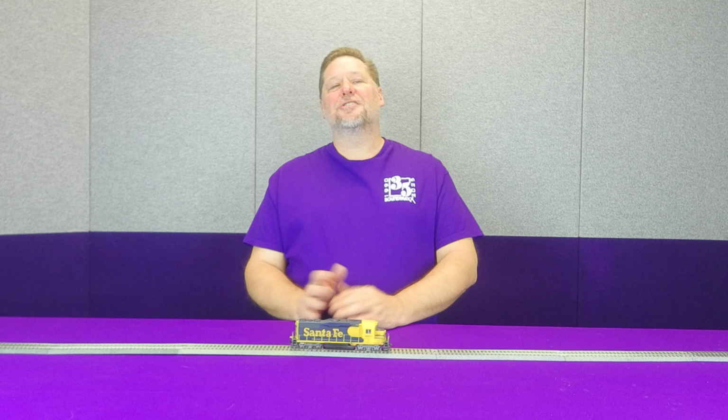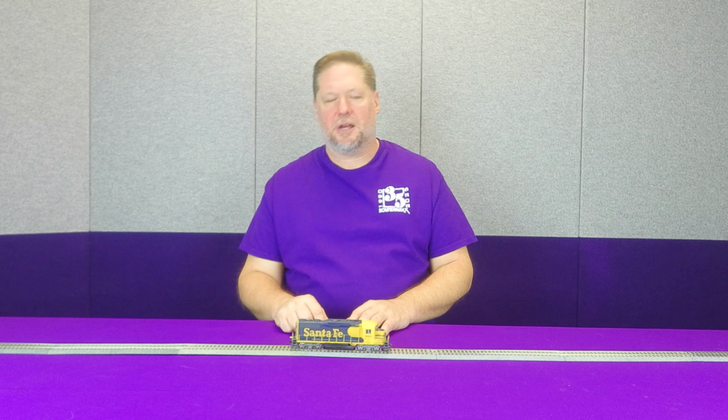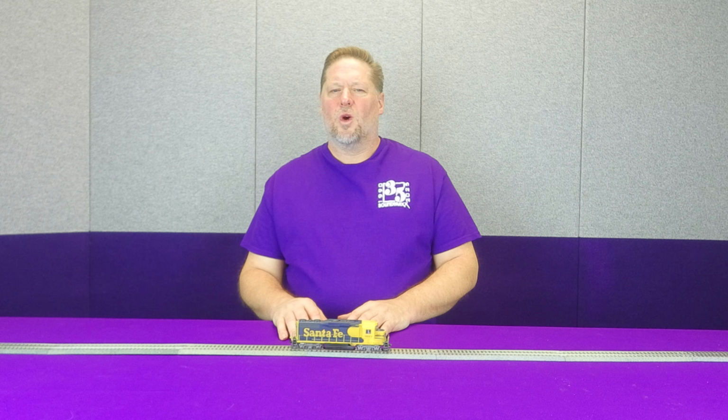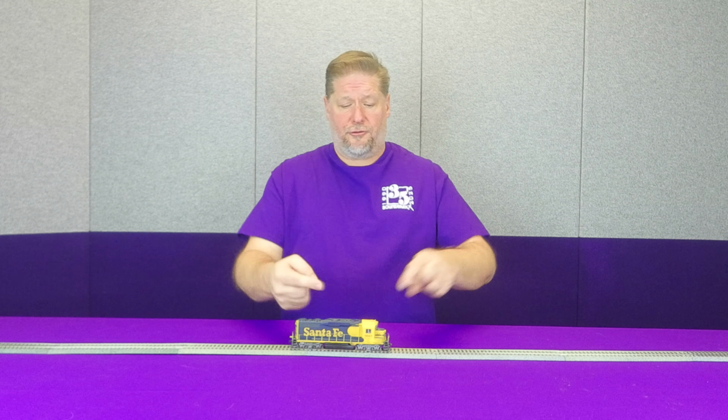Speaking of installers, the other thing CV29 can do is, let's say you get all the way done with your installation and you realize, oh crap, my headlight works, my backup light works, but the motor's wired in backwards. Now I've got to take the thing apart again. Well, the good news is you don't necessarily have to do that. You can use this part of CV29 to reverse the direction of travel. So now when you're moving forward, the throttle actually shows forward, because that compensates for the motor being wired backwards. The only caveat here is it also flips and reverses your direction of travel for your lights.